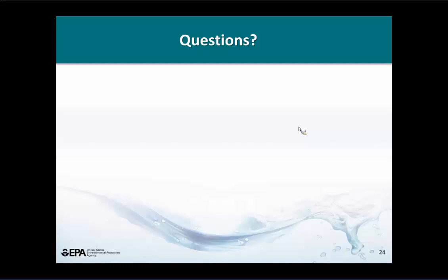Okay, but what happens if we really only want to try to use one model? Well, what's the most important parameter you're looking at? Nutrient runoff, harmful algal blooms, surface water interaction? I would use SWAT. If the most important thing is combined sewer runoff or stormwater runoff into a hydraulic system, I would use SWMM. I would say that was a very good answer.